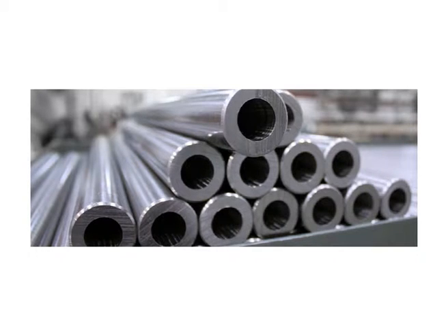Two of the essential parts of a weapon are barrel and action. Manufacturing processes, specifications and tests are conducted to assess the limit of barrel life and non-failure of action. Before any barrel is accepted for use, it is proof-fired with a high load test cartridge, which is capable of producing at least 40% more pressure in the barrel than the load which it is intended to withstand.